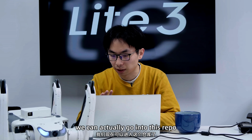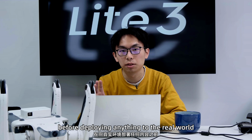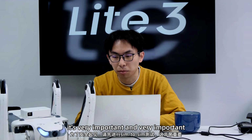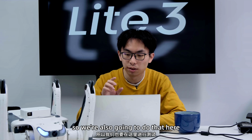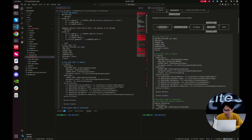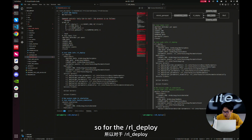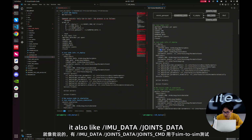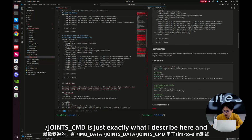Okay, now we can actually go into this repo. Before deploying anything to the real world, it's very important for safety to do a sim-to-sim test first, so we're also going to do that here. This is the ROS2 topic introduction. For the RL deploy, the IMU, joints data and command are exactly what I described here.